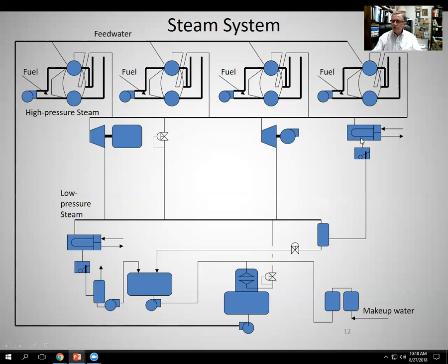This is, again, our heat exchanger with a steam trap on it. And the condensate is coming into this tank here. This is called a flash tank. So when this condensate goes from the high pressure to the low pressure, some will jump into the vapor state, and that will flow into the low pressure header. The rest will flow into the condensate return tank.